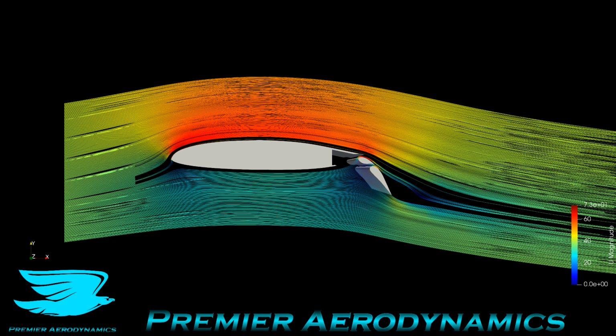But to have a lift coefficient of 3.2 is phenomenal compared to any other airfoil really. And the way they do this is through this system. So how does it work? So we have the typical airfoil over the front bit, and the air rushes over, and you can see that the flow is colored in the velocity from blue to red, red being 73 meters per second. As you go over the top, it accelerates, we all know that. Then as we get to the trailing edge part of the first part of this system, the flow then starts to go over the other two sections, but if you look at the bottom streamlines, they start popping up and over these other airfoils. So let me draw a picture to illustrate what's going on.